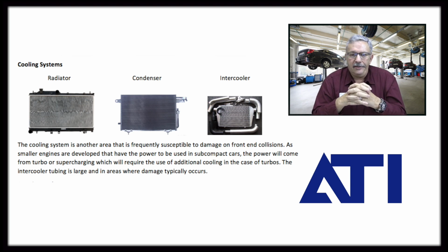Condensers. This is a real sticky subject, because if someone has, I'll give you for instance, an air conditioner compressor clutch disintegrates, and now the shaft goes back in and goes into pieces inside that system, I've now contaminated that system.